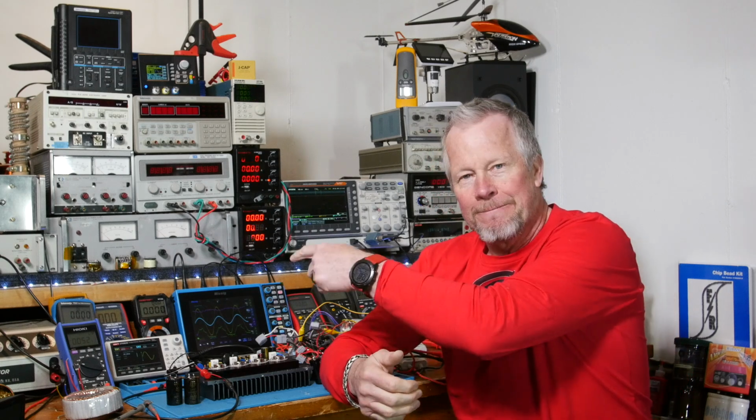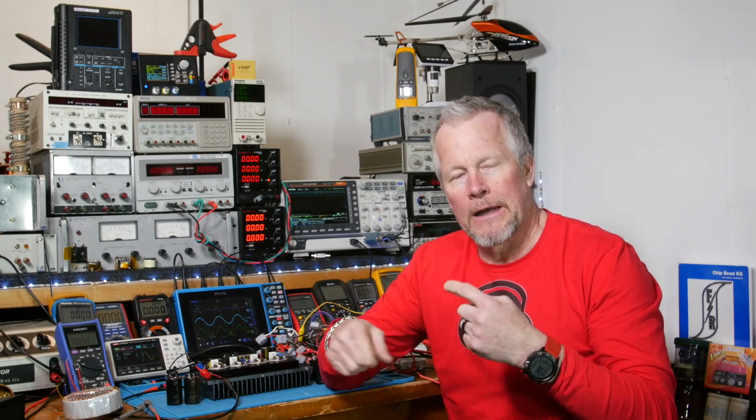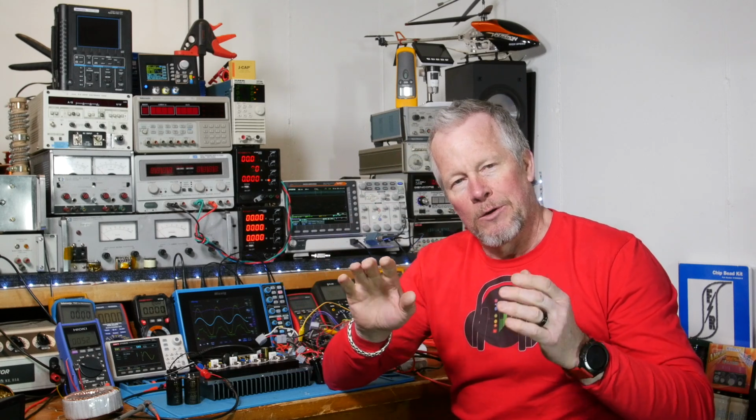Alright guys, a little explanation if that doesn't make sense to you. I wanted to show you the video of the scope first, before I talk a lot. Here in the States, our power frequency is 60 hertz. Once you go through a bridge rectifier, you double that to 120 hertz. You're taking the negative pulses and putting them up on top, so what used to be negative is now positive. You get pulsating DC on the other side of the bridge rectifier at 120 hertz.